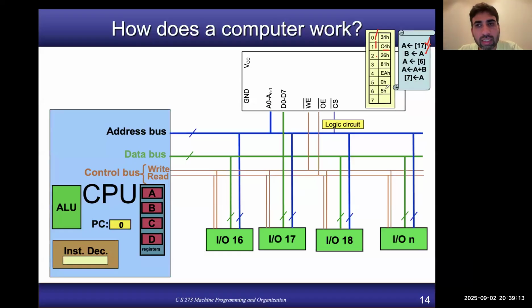Now we want to look at how this program which we have burned in the code memory of the AVR is executed. Initially your PC contains the value 0, pointing to the first instruction. This address PC0 is the address of the first instruction, so you put that address on the memory bus and say you want to read from this address. Basically you read the instruction from the code memory and bring it into the CPU. Here you are enabling the read signal. Yellow means that you are pulling it down.